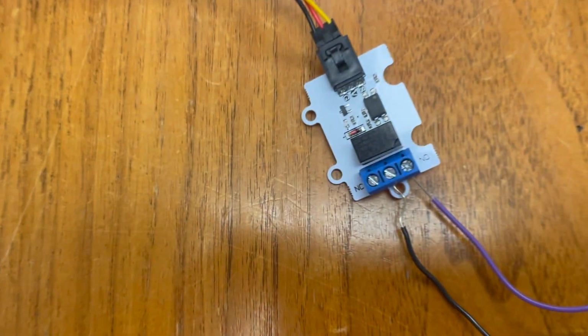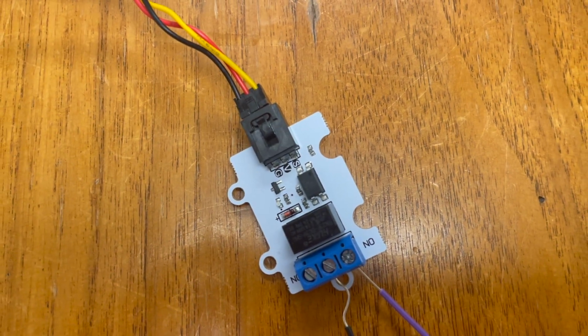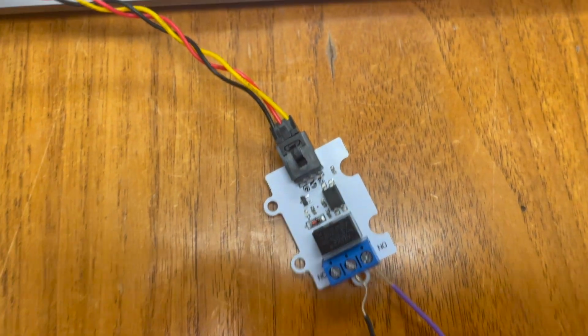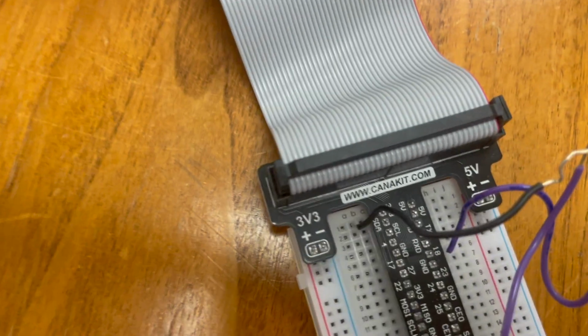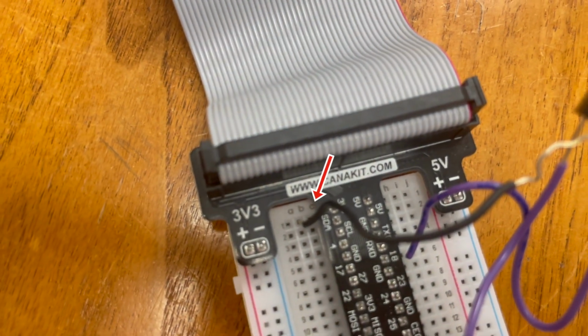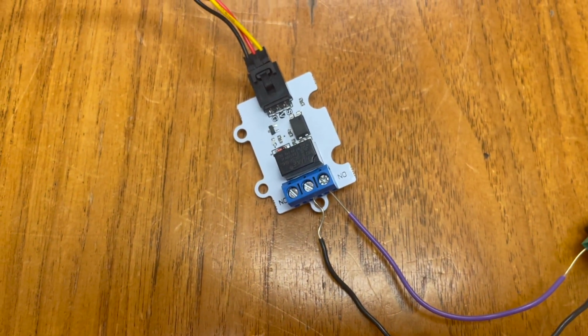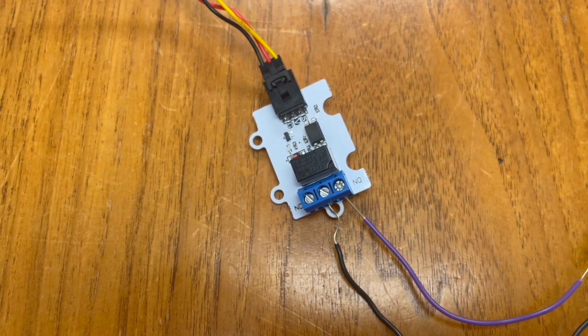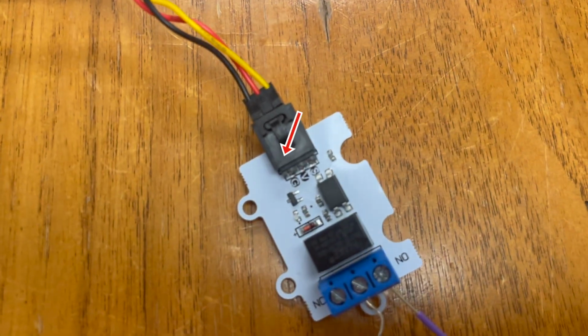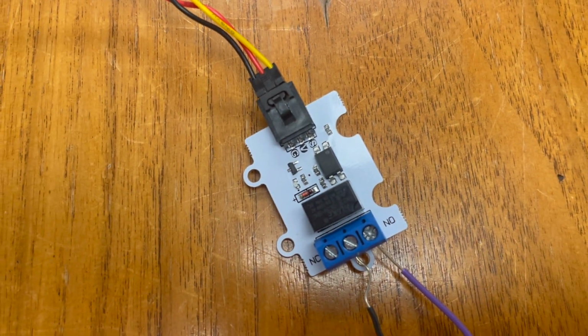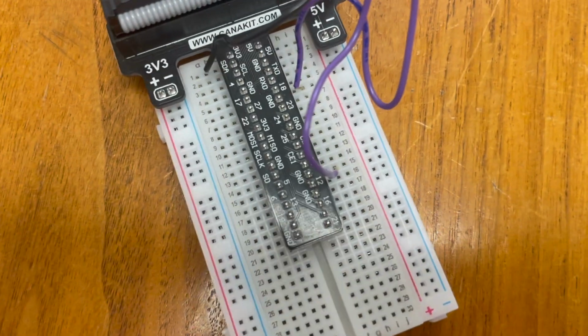The V, which stands for voltage, wire is connected to a 3.3 pin and is shown by the red wire. This more or less lines up with the 3 voltage requirement of the relay module, so no level shifting is required. The G, which stands for ground and specified by the black wire, is simply just connected to ground.